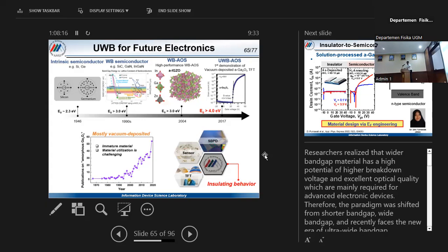But for example, amorphous IGZO is very sensitive to light, especially UV light. If you expose the amorphous oxide semiconductor to UV light, the current will increase. That is the way it senses light. Another way of using amorphous IGZO or oxide semiconductor as a sensor is for sensing moisture or oxygen.